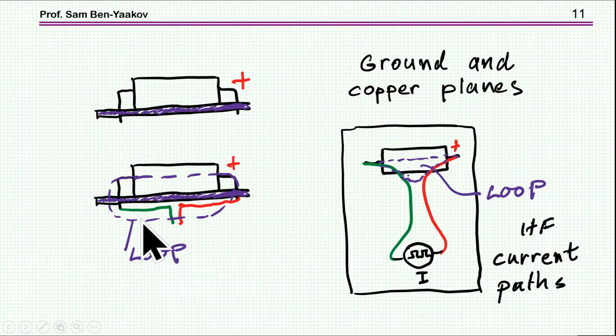This is part of the fact that this capacitor has two wires on the two sides, and you have somehow to get to them, and therefore you will have this loop here no matter what you do. There's nothing you can do about it. So you cannot say that this belongs to the PCB. This actually belongs to the capacitor.